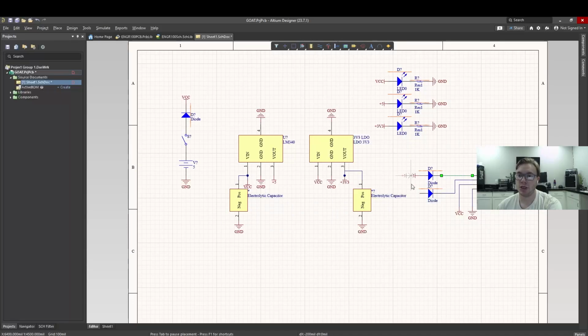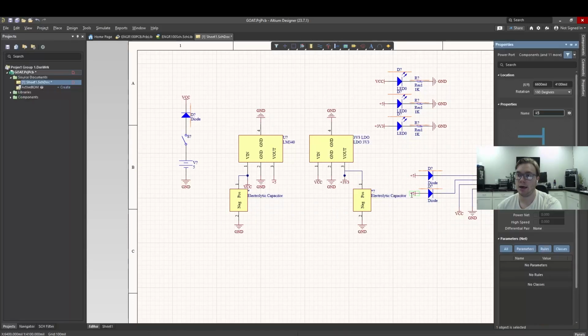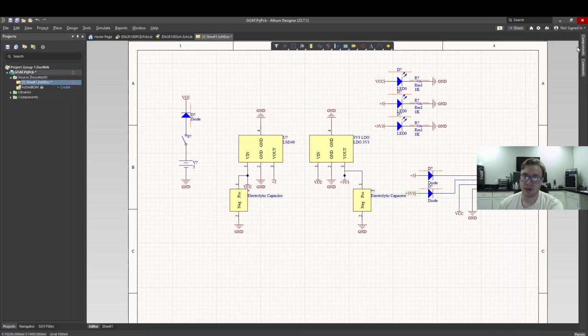It's a lot cleaner. It's much easier for somebody to read through your schematic and either see what's wrong or just generally understand what's going on when you use net labels. If I did not make net labels at work, people would get mad at me. So I think that's it. I think that's our whole schematic. It looks like the design that's on the slideshow.